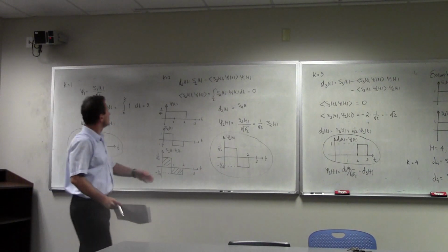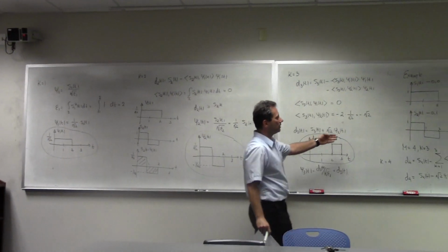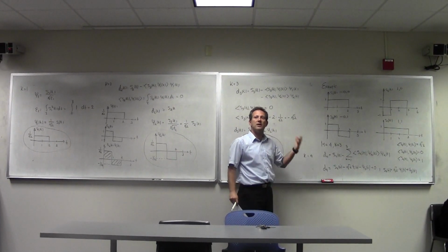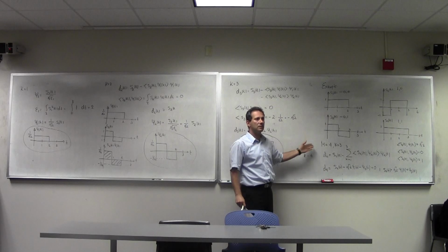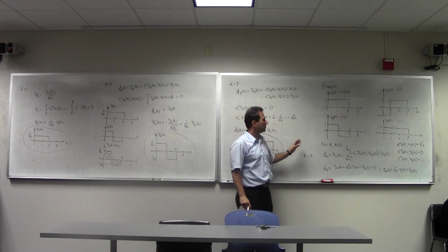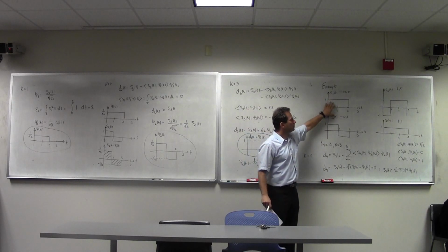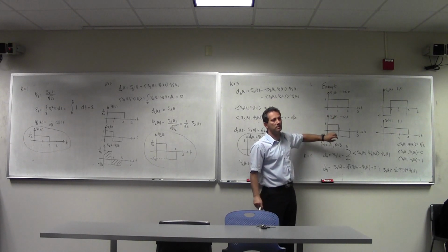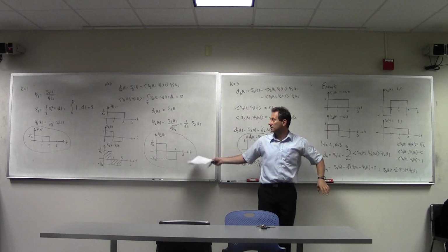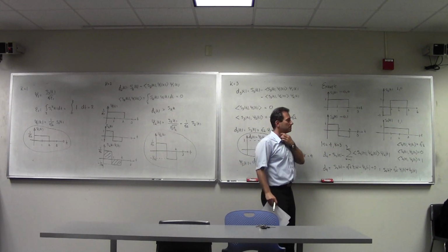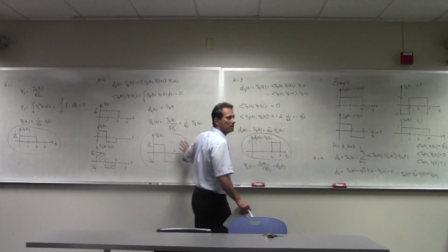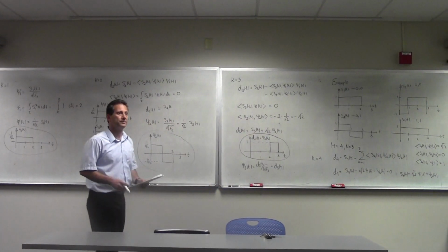So if I were to use this for signaling, the type of signaling I'm going to be implementing would be three-dimensional signaling, because I have three independent vectors, and I'm going to be forming my constellation space, or my signal set, by mixing my three basis vectors, psi 1, psi 2, and psi 3. You can express each one of these as a linear combination of these three.